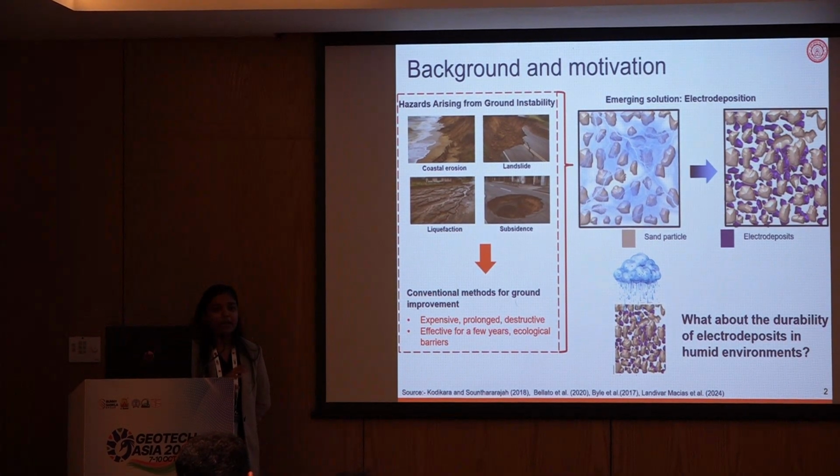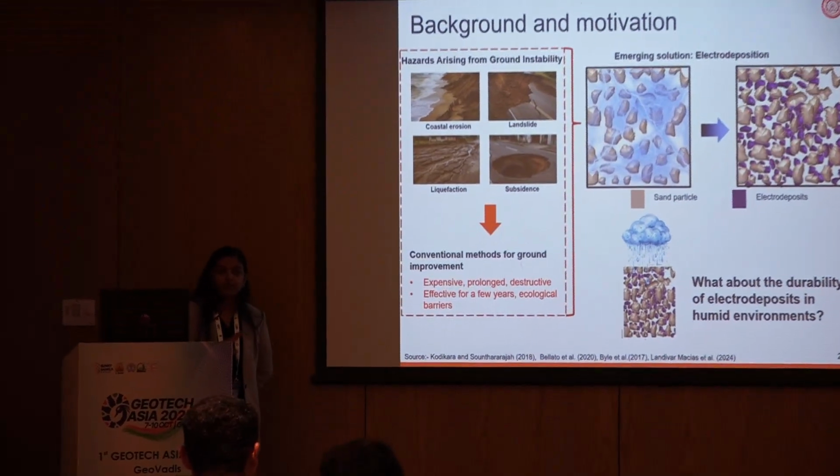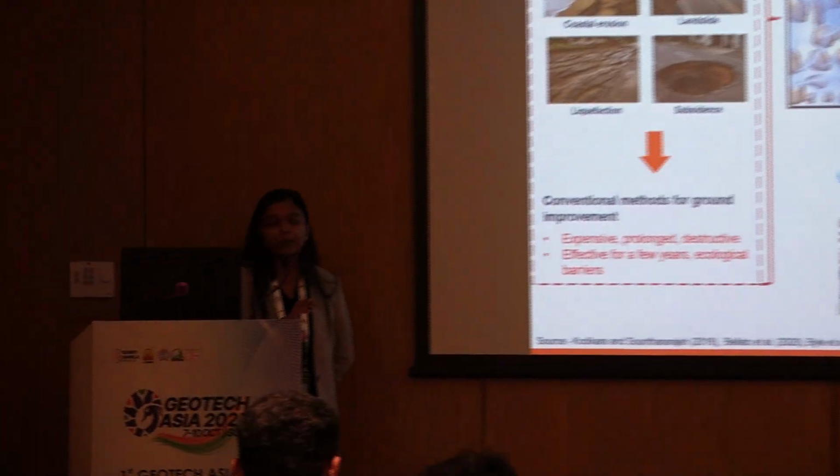If we apply an electric field in the presence of some chemical solution to the sand, it will introduce some solidified compound in the pore space of the sand, which increases its shear strength and reduces its permeability, so that we can mitigate hazards like landslide, liquefaction, and subsidence. However, there is no study on the durability of these electrodeposits under humid conditions.